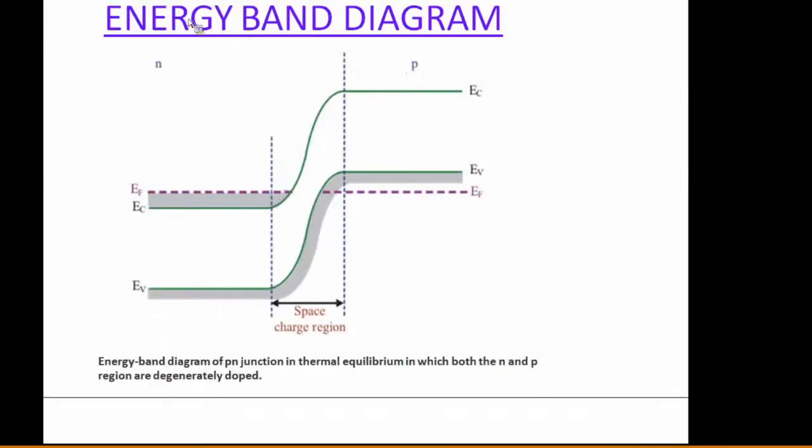Now I am going to direct you to this. See the energy band diagram. This is normally for N type and this is for P type. See the Fermi level. You may have one doubt: why will the band bending structure be like this only? This structure comes from the doping concentration. Because of the heavy concentration, it looks like this. What is going to happen? See, this is a conduction band. Here electrons are there. Now in this valency band, what is there? Holes are there.